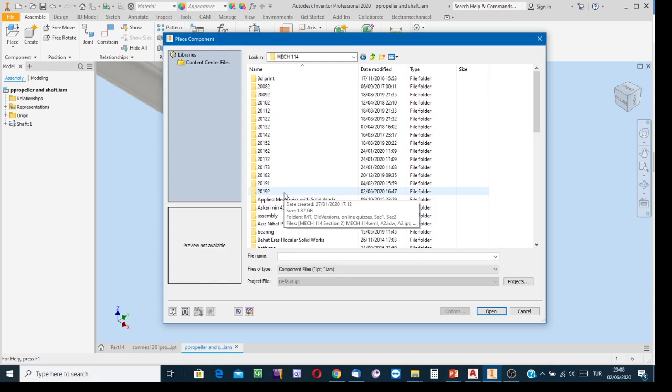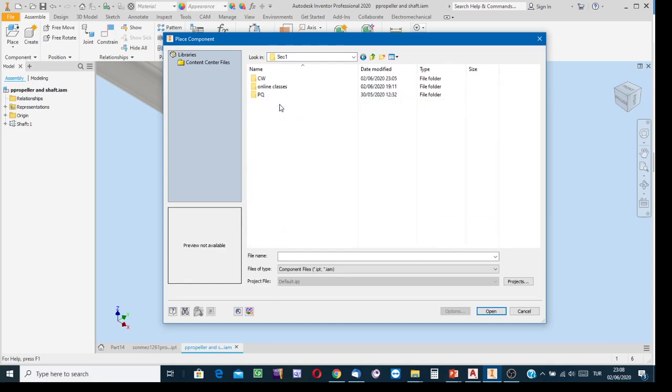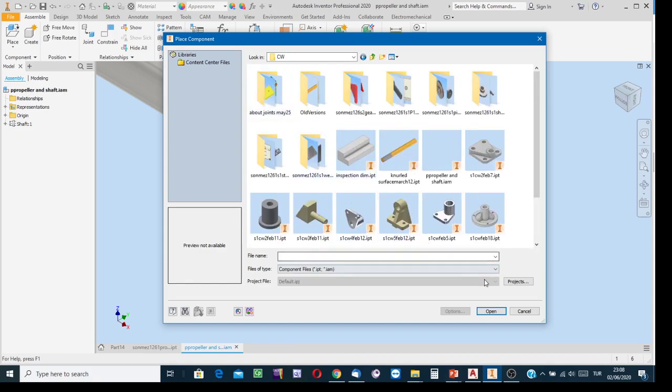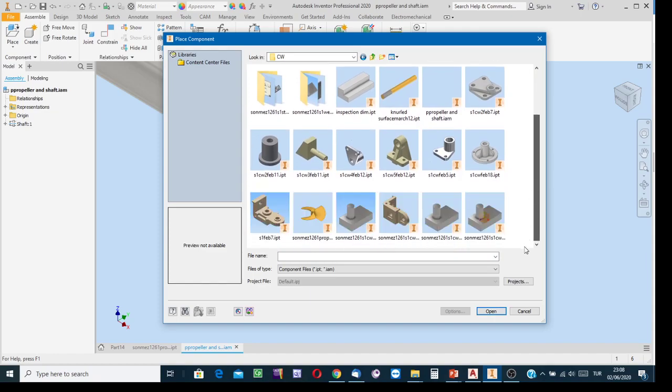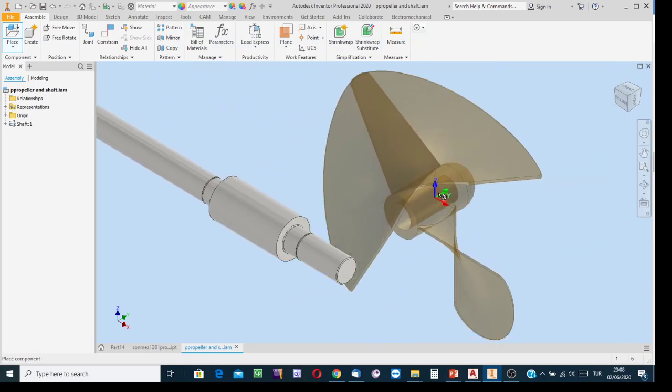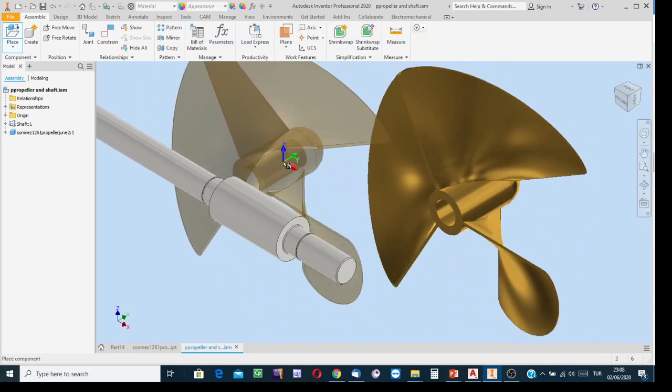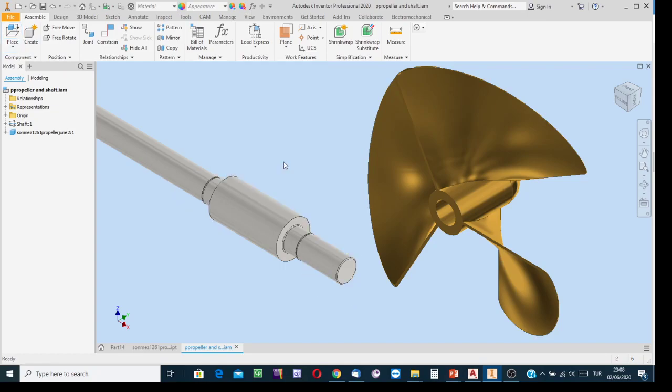But assume that first I defined the work as a project, created the project folder, and then in the content of the project, created such components and also the assembly. Assume. Yes, find the model of the propeller. Here it is. And then in the assembly environment, first arbitrarily locate it with a click, press the escape button, and then the rest is the mating stage.